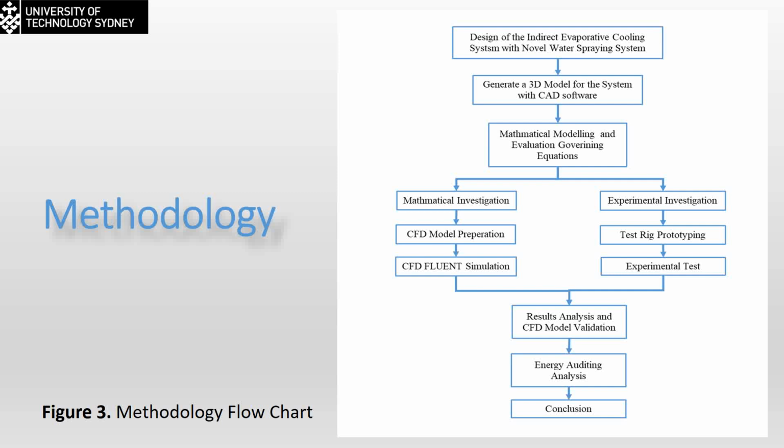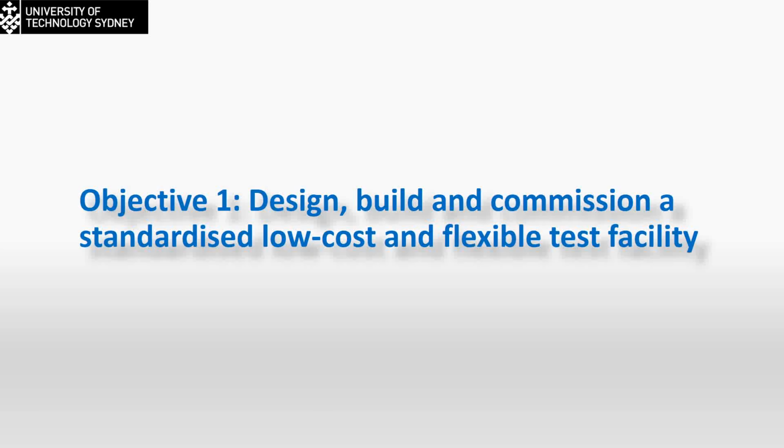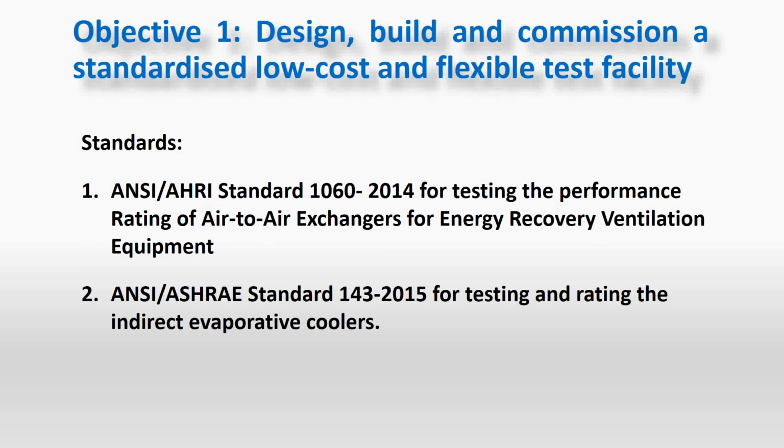So for objective number 1, the test facility must be standardized. Otherwise, we cannot say that this is going to be accurate results. So I took 2 standards. The first one is for testing air-to-air heat exchangers for energy recovery ventilation equipment. And the other one is for the testing of indirect evaporative coolers. Both are American standards, but they are actually the only standards we have for both testing.